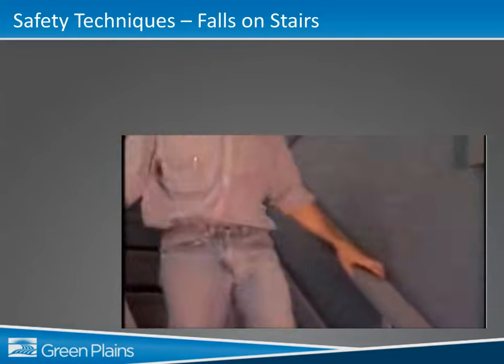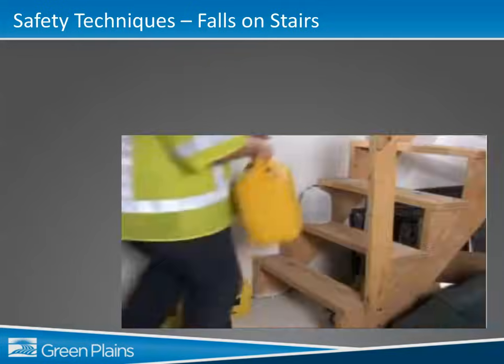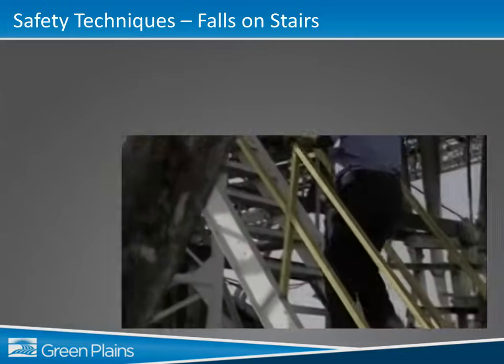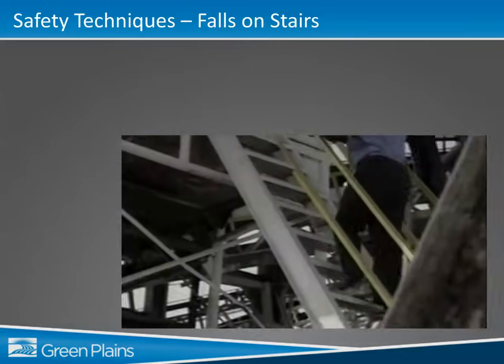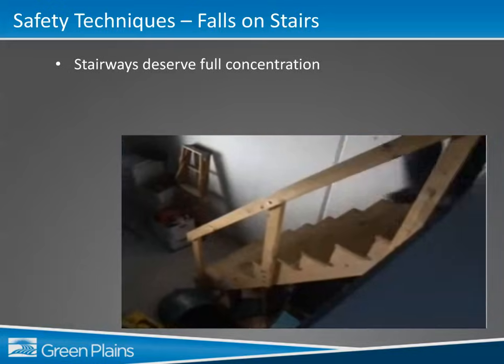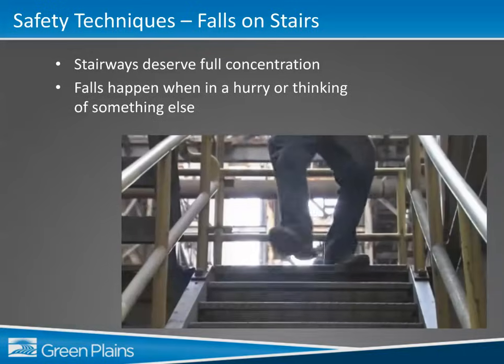Trips or falls on stairs can happen going up or down a flight of stairs. Only a slight difference in the height of subsequent steps can cause a person to trip and fall. 80% of falls on stairs occur on the first two or last two steps. 90% of stairway falls are due to unsafe behavior. Stairways deserve your full concentration.